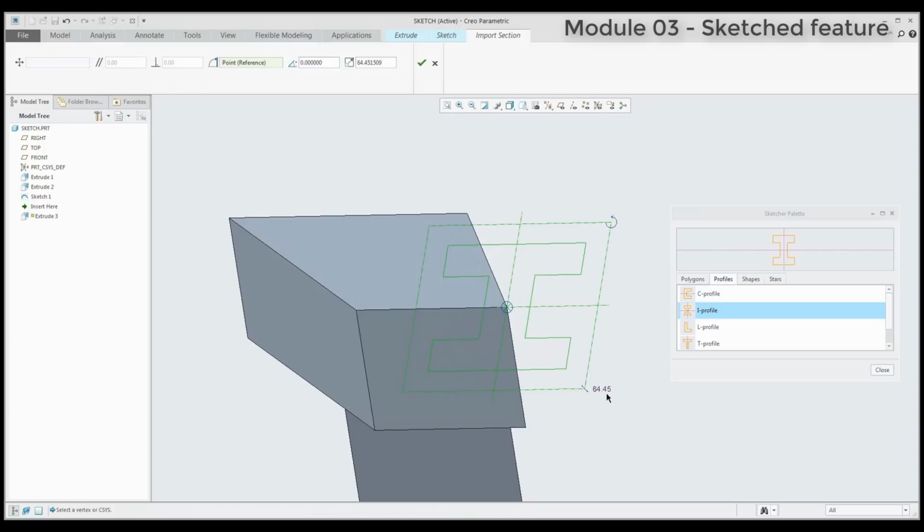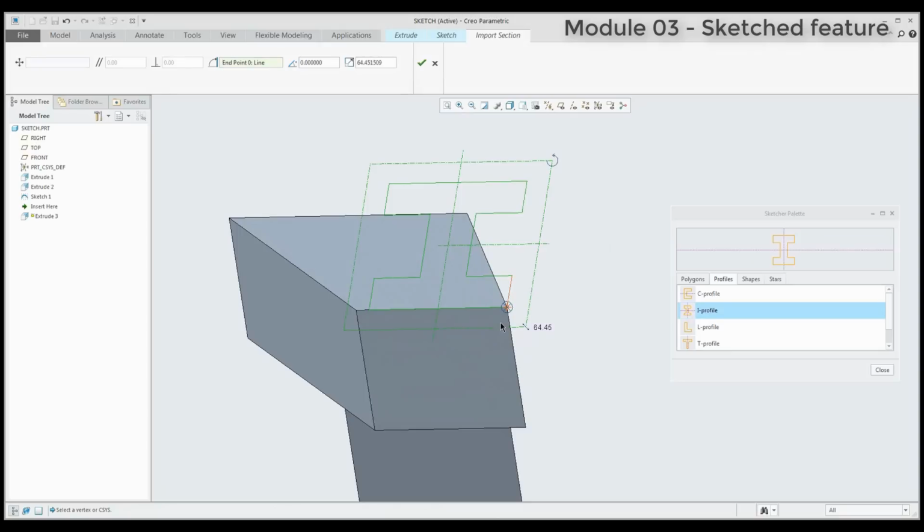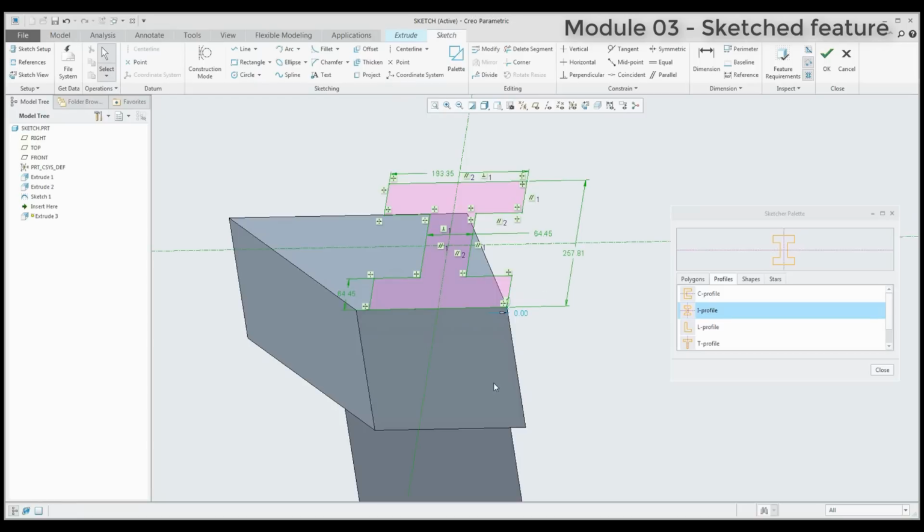I can change the scale, I can spin that sketch, or you can select the right mouse button and move the moving point. So right now the system will spin that point to my selected sketch. So it's not a problem, you can confirm, and again you can create your custom dimensions or edit the sketch.